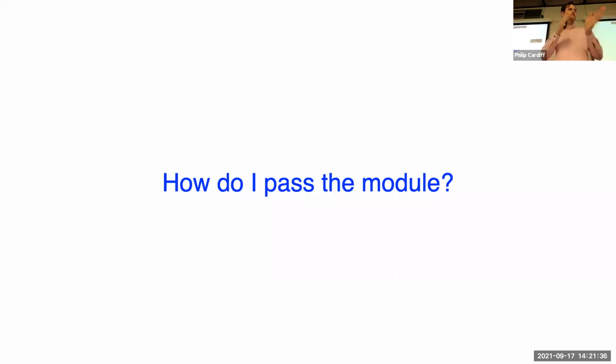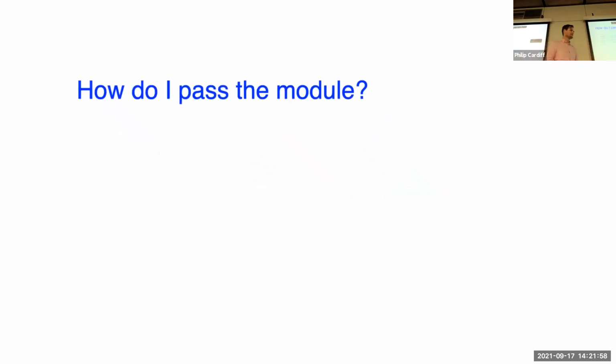If you learn a few different simulations, what I'm focusing on is that you just know the steps. All of these softwares have the same steps: boundary conditions, meshing, geometry, materials, loading conditions. If you just know that any software for simulation has those steps, then you can learn any software relatively quickly. Okay, the buttons will look different in different places, but it's the same thing underneath it. So that's why we use 3.